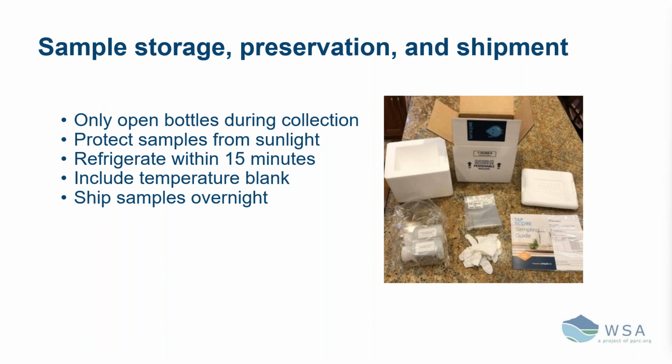So, sample storage and preservation and shipment. Only open your bottles during your sample collection, protecting your samples from sunlight and from the outside elements. Refrigerate, get your samples on ice at least within 15 minutes. Include your temperature blank and ship your samples out overnight.